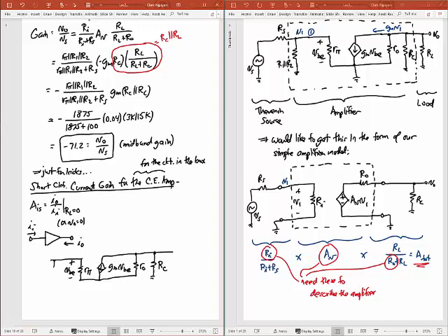And out here I have this resistor, R1 parallel R2. And so in this case, I'm going to shove in a current. There's my Ii. I'm going to ground out my output. And I want to measure the output current going into that ground. In this case, going out of that ground, because I'm taking that as my polarity for this.